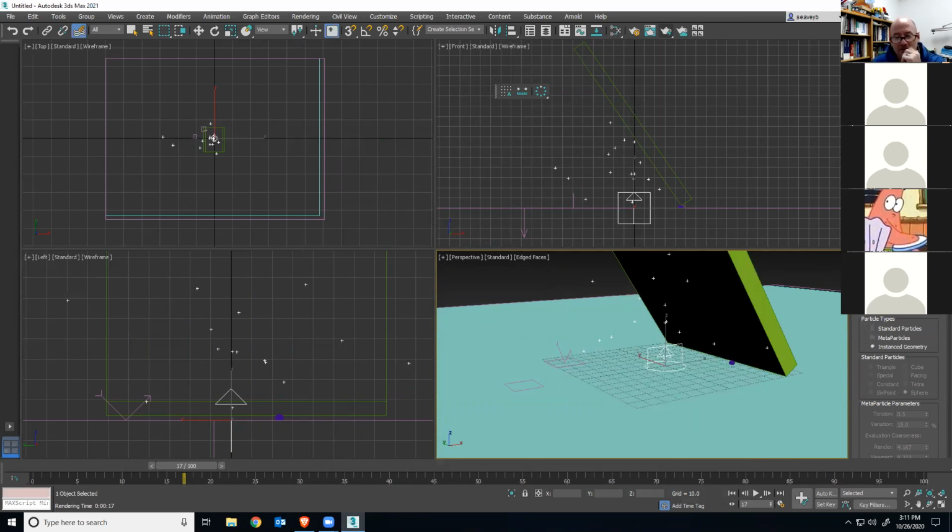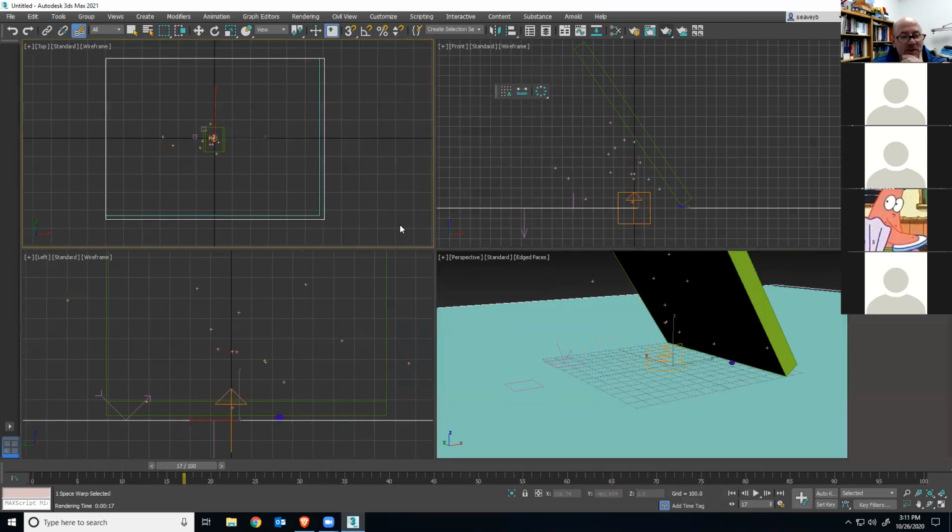Oh yeah, I wanted to change the bounce on the ground and put some friction on it because they're sliding all over the place, right? So I'm going to knock the bounce down to maybe 0.4-ish, with a little variation, maybe 20%, and some good friction going on so they slow down. It goes up to 100%, so I don't know, 28, 30. Let's see what that is.